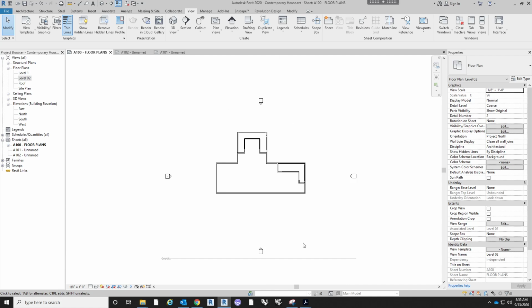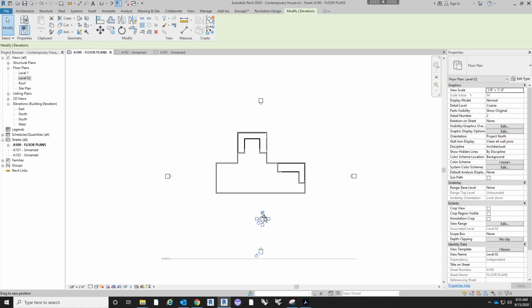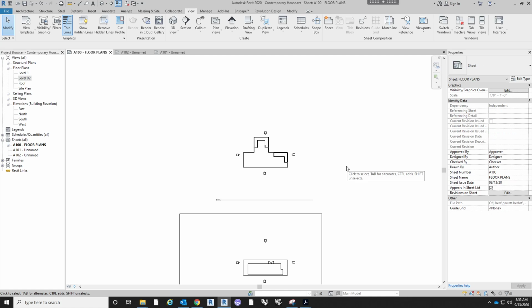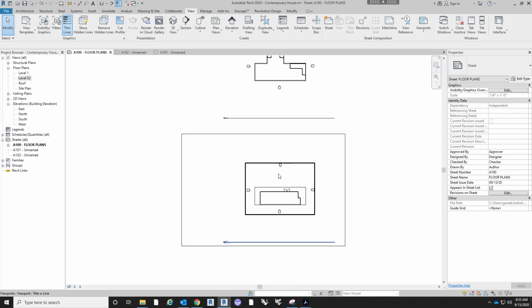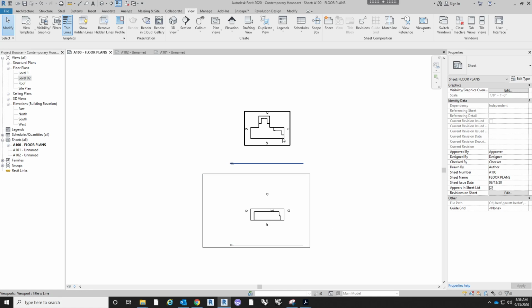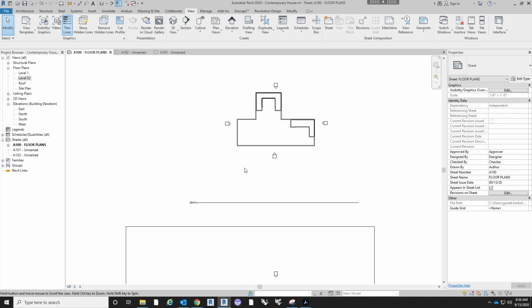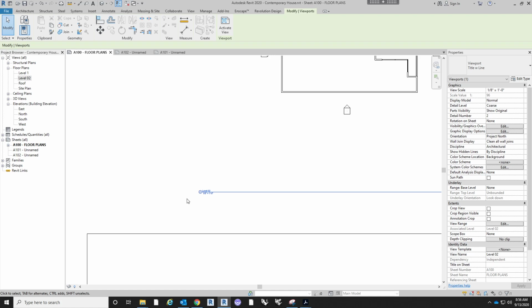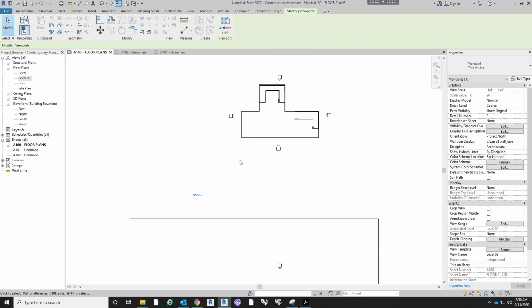That opens up the drawing and lets us manipulate any of the Revit elements that live in there that we can see. And all we'll do is just drag the elevation tags closer to the building, just so that it makes the drawing a little bit more concise and tight, and it does that automatically down here as well. All right, so the other thing that this populates is a title for the drawing, a drawing title.